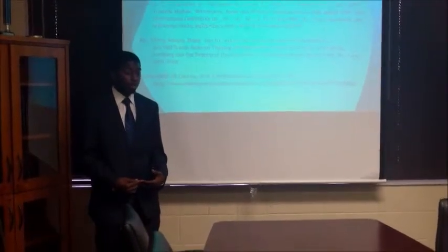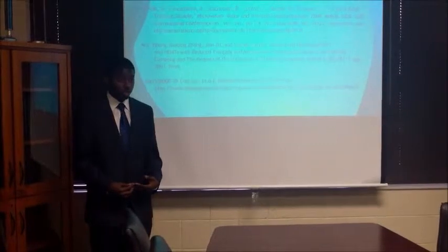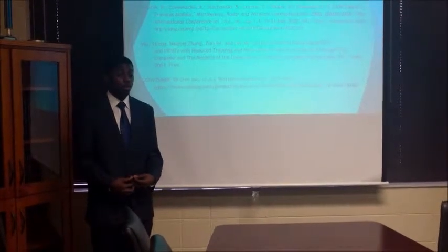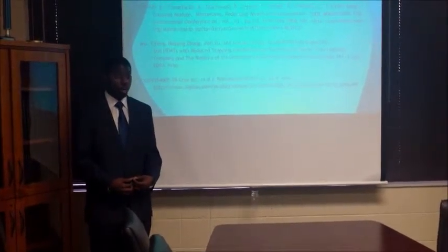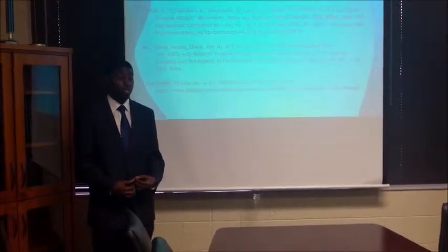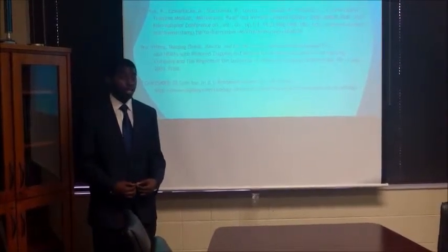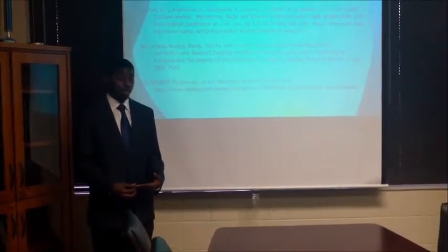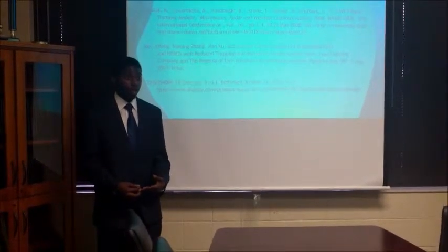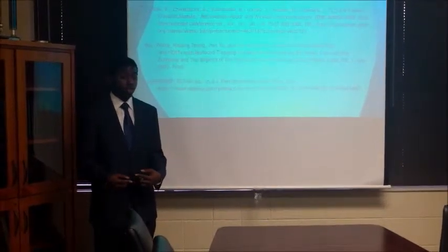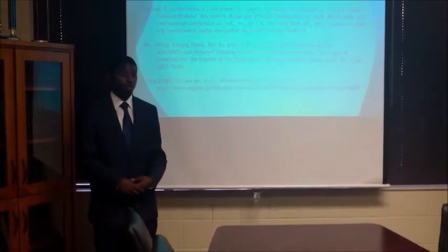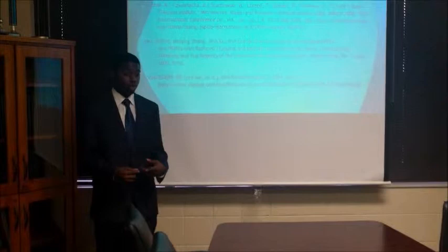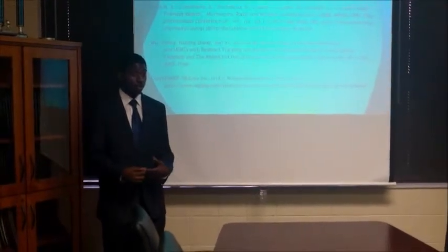So we chose to use an NPN BJT transistor, in which we will be using the Analog Discovery device to measure current. Unfortunately, the current through the BJT cannot be measured using the Analog Discovery natively. So we have 2 resistors in conjunction with the BJT, and we will use the voltage of one of the resistors and use Ohm's law to find the current through the BJT.